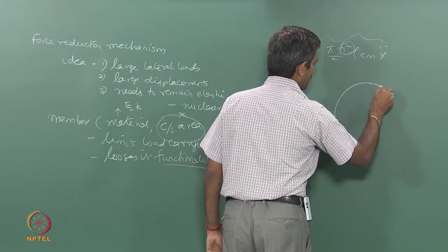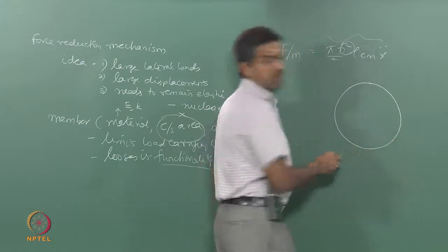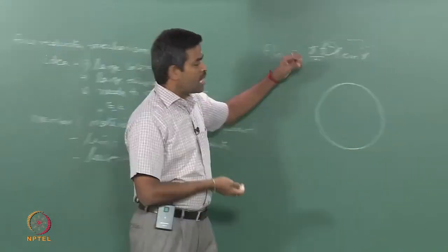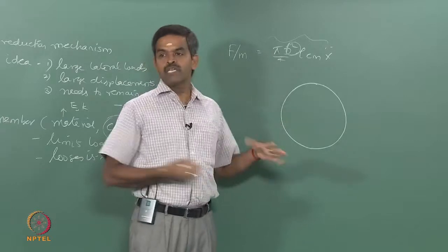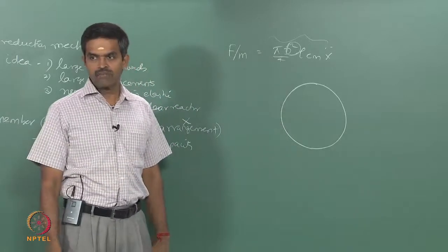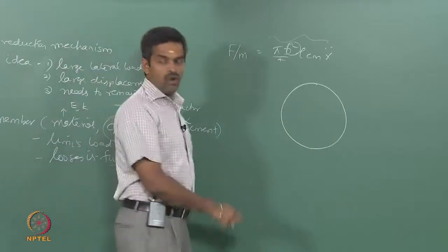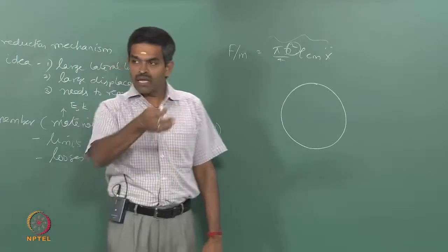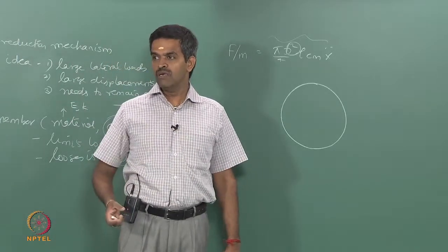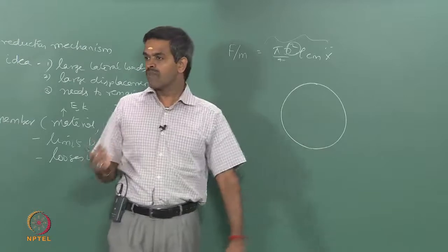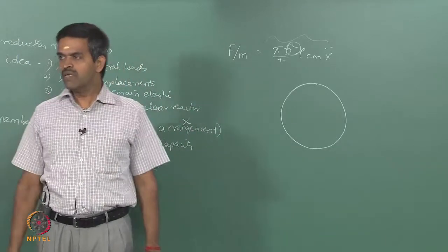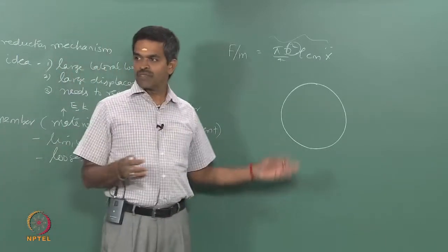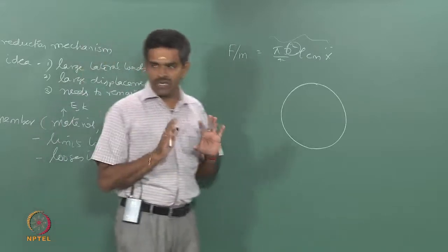Generally, offshore structural members are cylindrical in shape. We know the reason: the characteristic dimension of the member is always constant in any direction for a given force. Okay, that is why they are cylindrical generally. Square also has a similar tendency, but the diagonal length of the square is much more than the side of the square. So, the characteristic dimension will be more than the side of the square. Therefore, square is also not considered as an equivalent structure to a cylindrical one. Okay? Therefore, it is not correct.